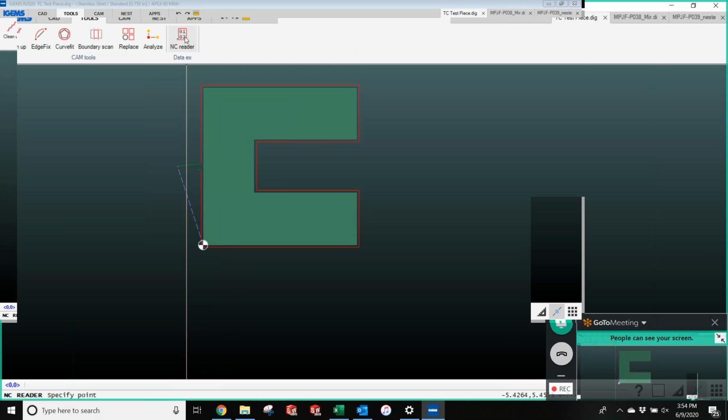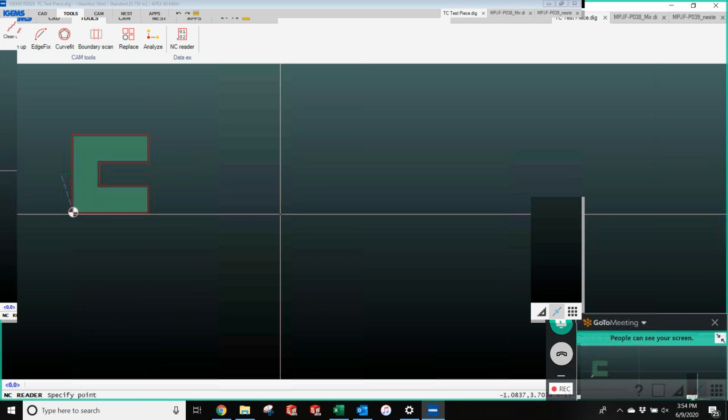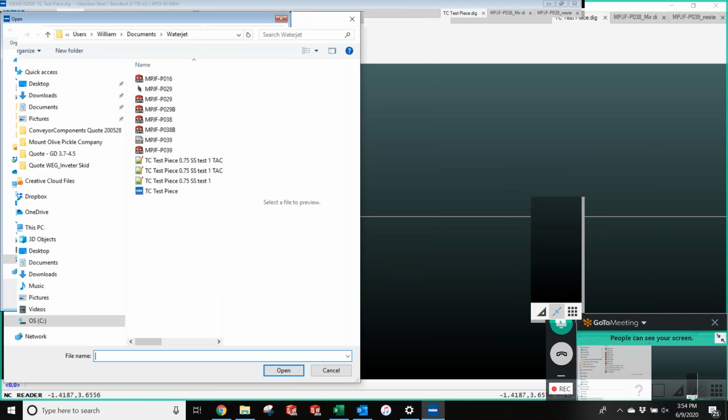So that'll also help in the instance where I've tried to do some holes that I plan on tapping afterwards, and the hole size looks pretty good. There's a little bit of draft, but probably no more than what a drill bit has anyway. But it leaves a little hanger, a little bump right at the bottom. Yeah, it'll probably help with that. You could also try doing a little more over travel or overcut on that.